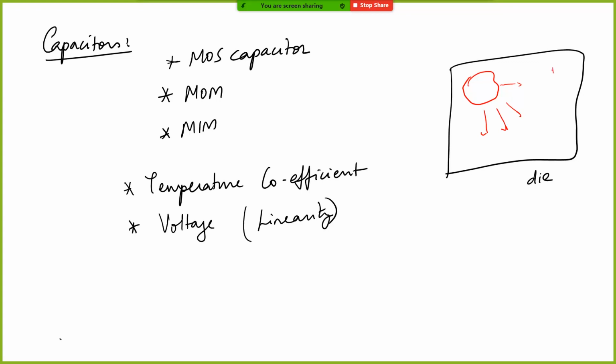So what you do is you feed in a fixed amount of current into the diode, and you measure the voltage of the diode, and this voltage will basically be a function of temperature. Basically this will tell you how hot the chip is in that particular area. And so thermal mapping of the temperature of the chip also happens, and this information is used to do thermal shutdown of chips if the heat becomes too much.